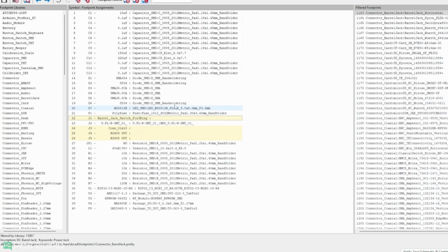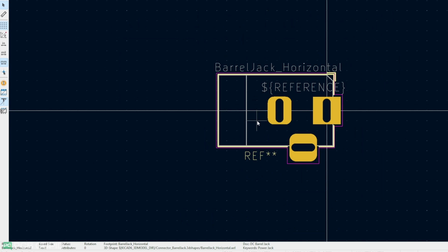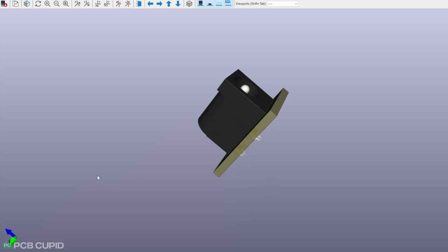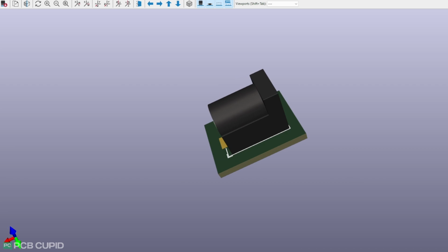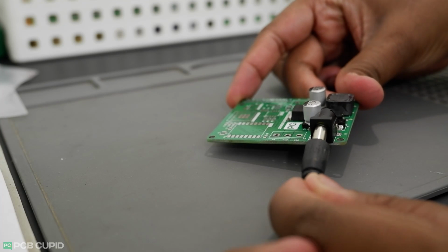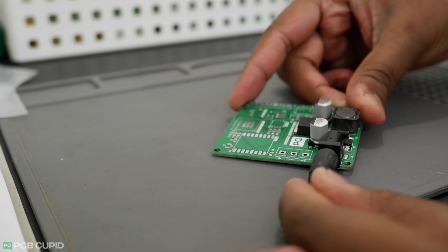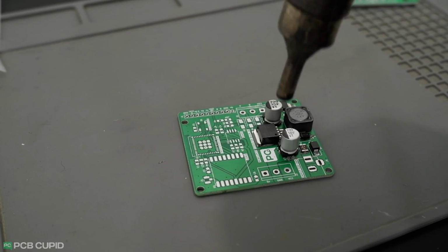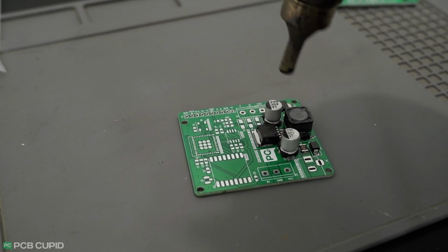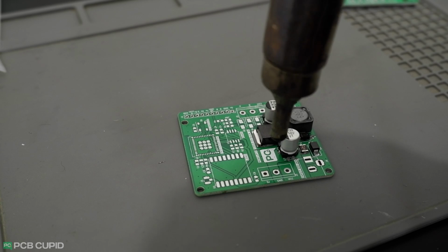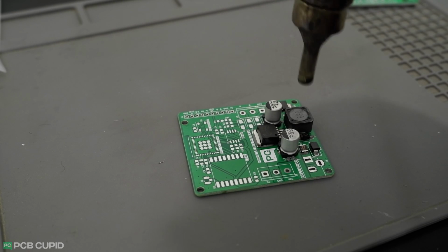Now, most of this footprint is shortlisted and assigned to the components. But if you notice, I have left a few components unchosen. That's because there are some features on the board that need through-hole components, even though it can be avoided. The best example would be the terminal block and the DC jack. Using the through-hole version of these components will make our PCB more robust and easy to use. I know this will increase the cost, but my idea is to assemble all the SMT components through an SMT machine and solder the through-hole components manually, or give it like a kit where the user can install them.